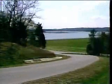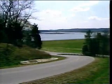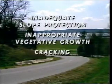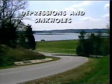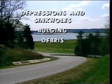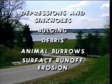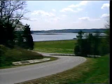Well, we've had a chance now to look at the remaining embankment deficiencies of inadequate slope protection, inappropriate vegetative growth, deficiencies of cracking, slides, depressions and sinkholes, bulging, debris, animal burrows, and surface runoff erosion. You may want to review the text sections on these deficiencies and have another look at the information presented there.